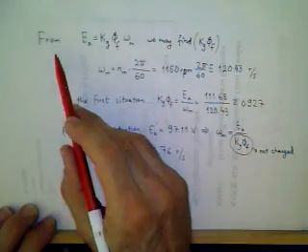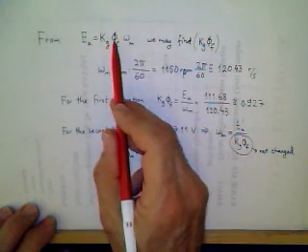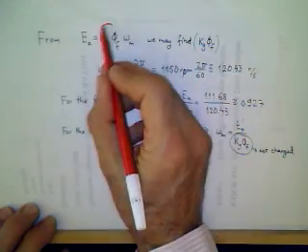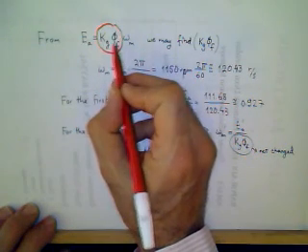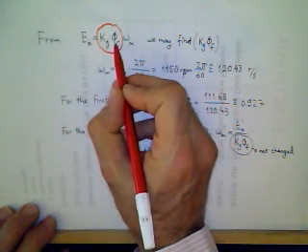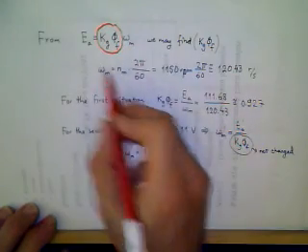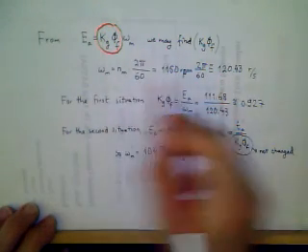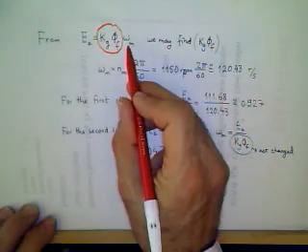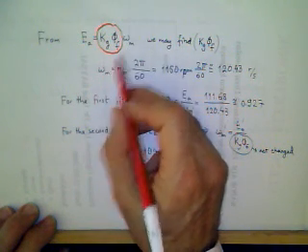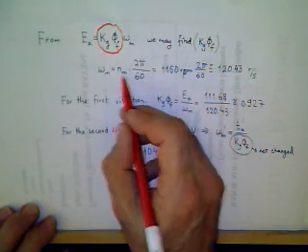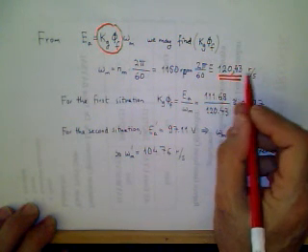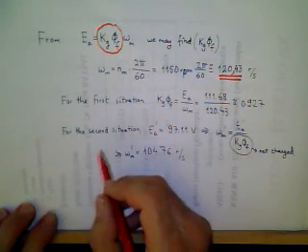So we know that from E sub A being proportional to the field flux times speed, we may find that constant, because this is a geometrical constant, and in the question it's mentioned that field is also kept constant. So omega m here is EA over that constant. We calculate the speed in terms of radians per second from the RPM value. So this value is 120.43 radians per second.